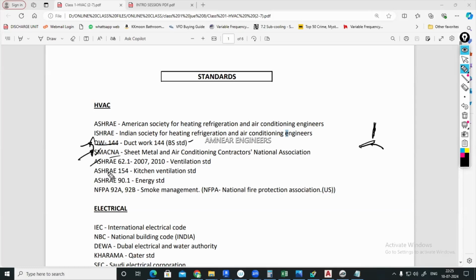We have discussed the importance of ventilation and indoor air quality. For example, when you are designing a particular space, as I told, to maintain the indoor air quality, we have to introduce oxygen-rich air to the spaces. How much it is matters, right? That's why with respect to the space that we are designing, for each person, how much air has to be provided? For each square meter of floor area, how much air has to be provided? We have to add them together. Accordingly only, we are calculating it.